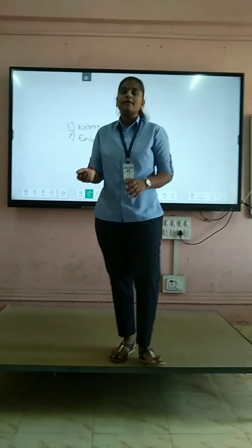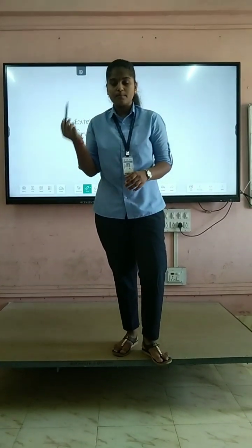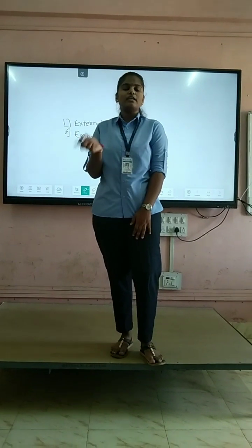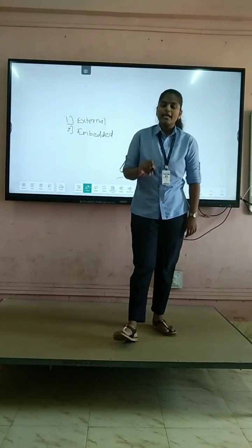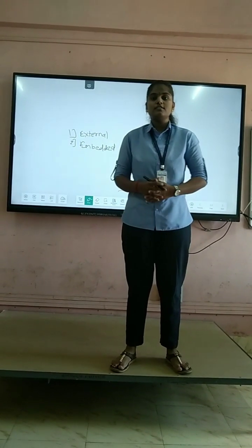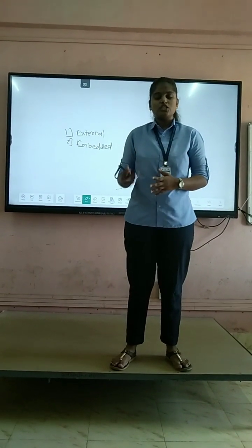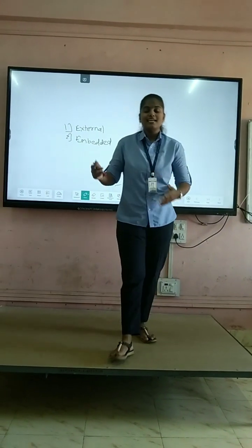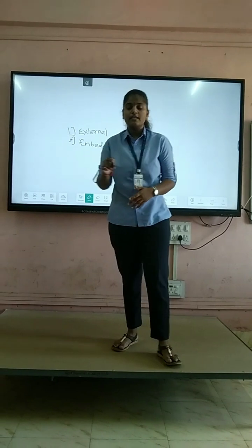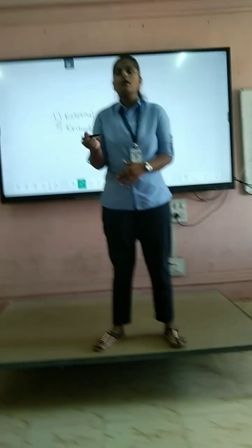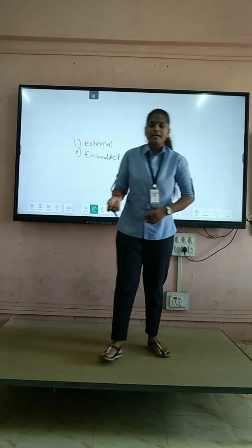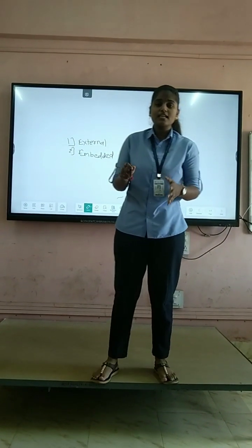Microcontroller is classified based on the bit configuration, that is 8-bit microcontroller, 16-bit microcontroller, and 32-bit microcontroller. The 8-bit microcontroller is used for various logical and arithmetic operations, such as addition, subtraction, multiplication, and division. An example of 8-bit microcontroller is the 8051 microcontroller. Then 16-bit microcontroller.